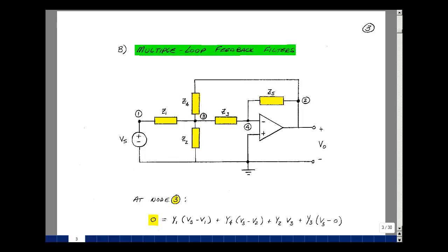You can see here, this particular structure we're going to analyze in just a minute has got an inverting amplifier here. Now with just R's and C's in these 2 impedances, you can only get real roots. We'll show why that's true in ECE 402. By adding a second feedback path, it's possible to create complex conjugate roots, which is what we need for this second order filter. See if we can analyze this circuit in terms of the impedances, and then figure out what kind of components we need to put in these boxes to make this particular case a bandpass filter.